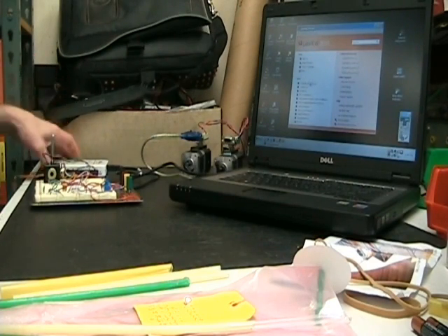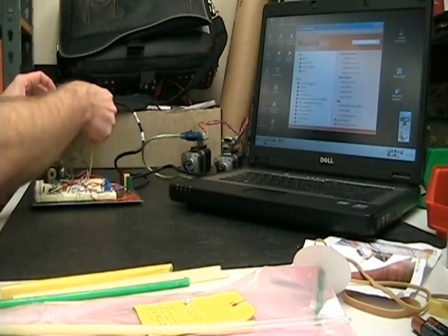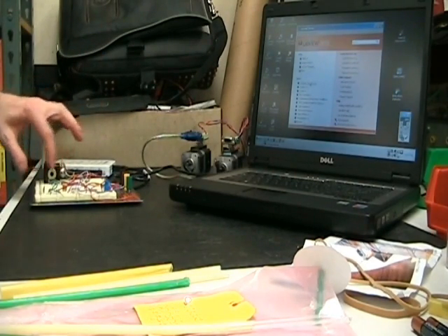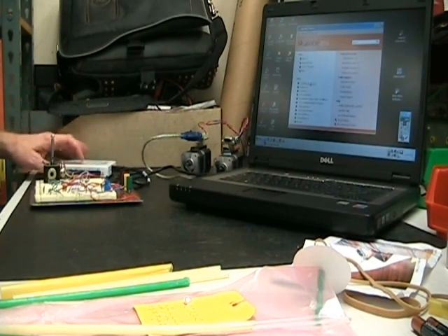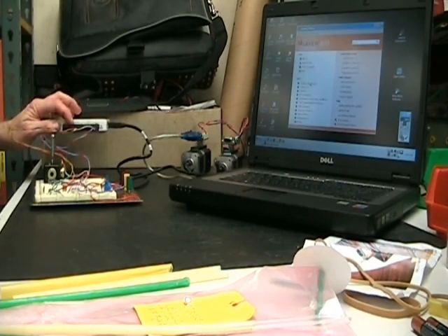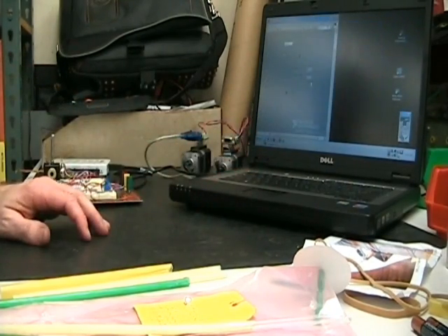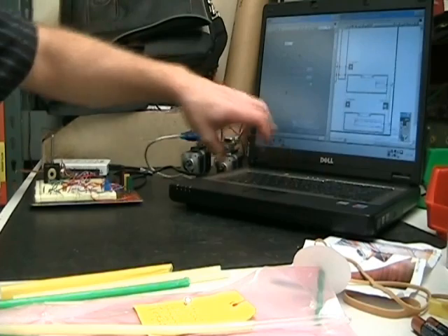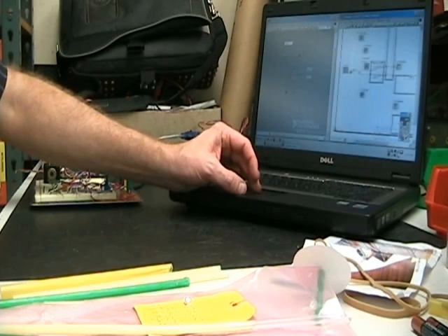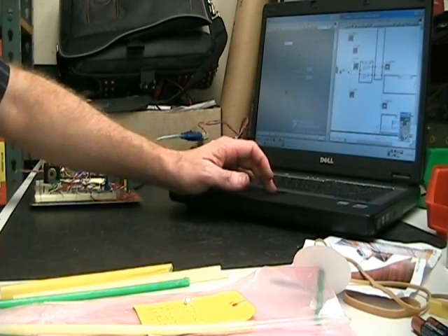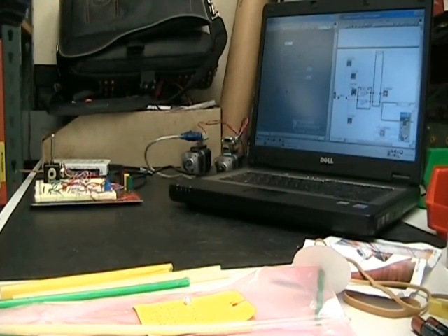So the joystick is wired to the MIDAC, and we're using 0 to 5 volts across each pot, and then the center arm of the pot through a resistor, just so that nothing can short it out. One goes to analog 1 and the other to analog 2. This is the LabVIEW, the complete LabVIEW program. We will look at individual parts in a minute. Oh, and there's also a power supply going to the QCI motors that's maybe out of view, but it's up there.